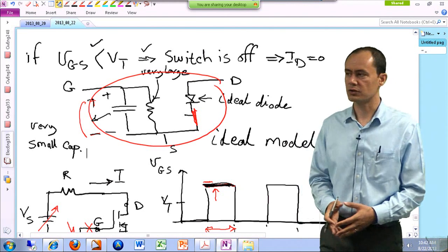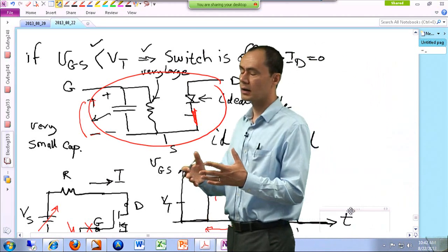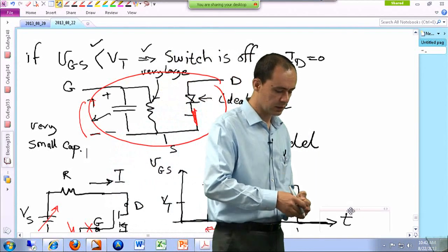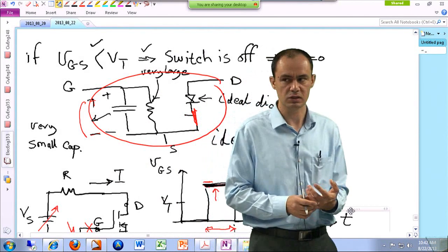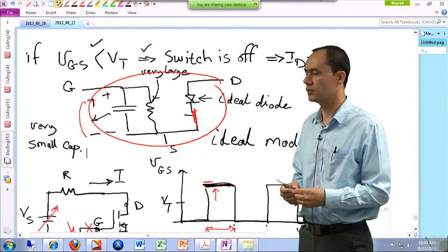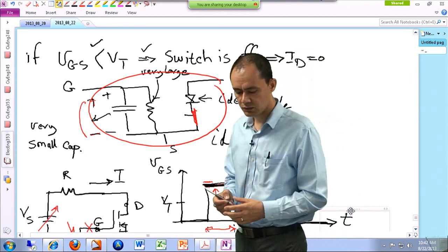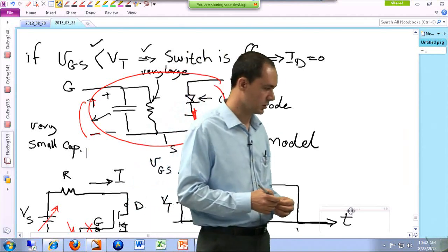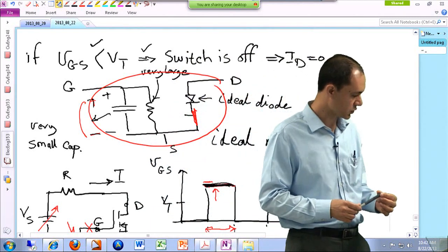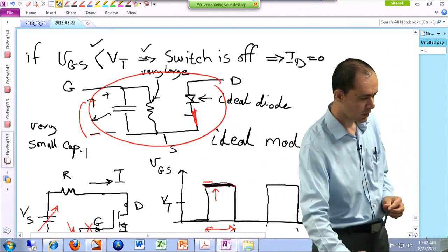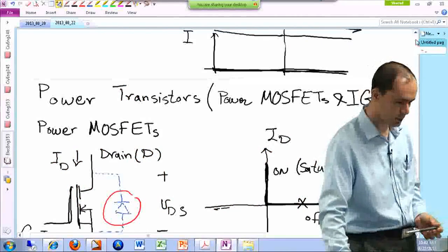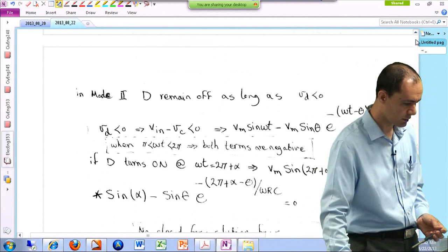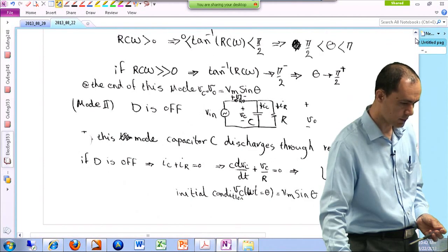As far as this course is concerned, MOSFETs and IGBTs are identical, meaning that you can unplug one of them from your circuit and plug in the other one. And that's actually the case in most cases, unless the voltage and current ratings of the devices are drastically different. Their gate signal requirement is pretty much the same, and their ideal features are almost the same. So as far as this class is concerned, we just assume they are the same. But in practice, in industry, they are not the same. Let me go back to this little table that I have over here and discuss that.